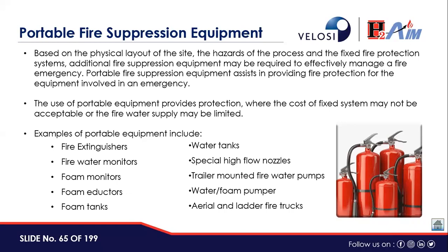Next question. Are pressure relief systems used for depressurization? Normally, see, it's a standard part of the plant design. You have to provide a relief system. Only PSVs may be open to atmosphere, or they might be leading to the flare system. And these relief systems are designed in accordance with API 521, and 520 is about the PSVs, but there are venting systems, flare systems, or burning pit systems, and all kinds of relief systems which are applicable on any given facility should be designed and installed.